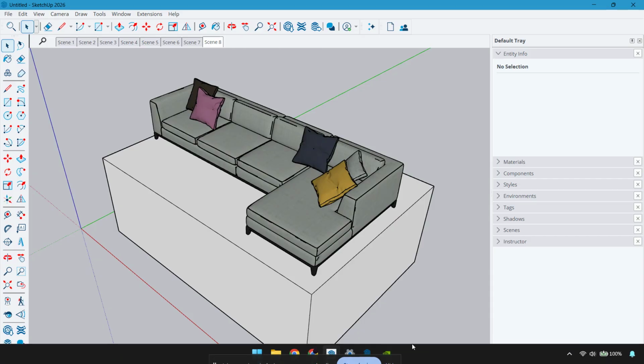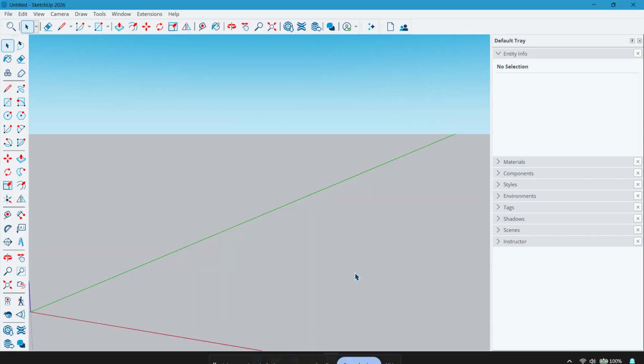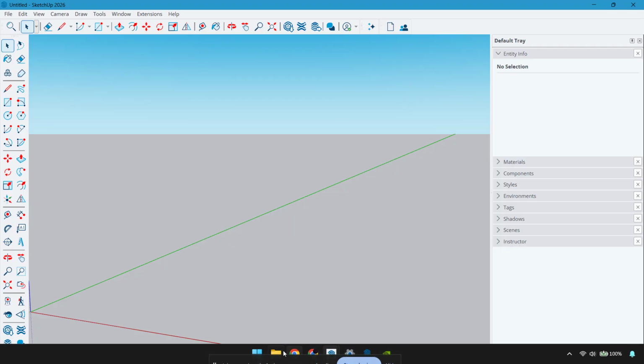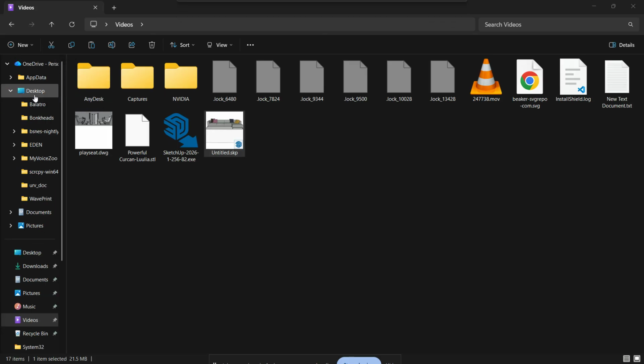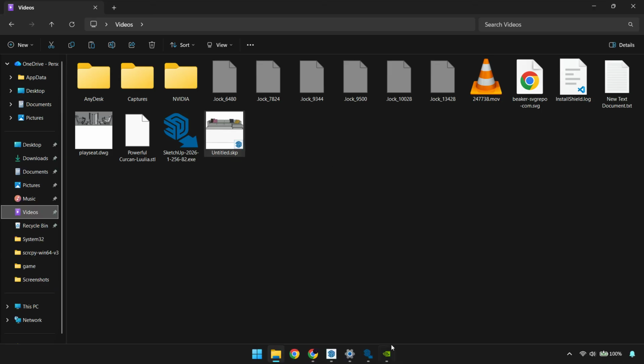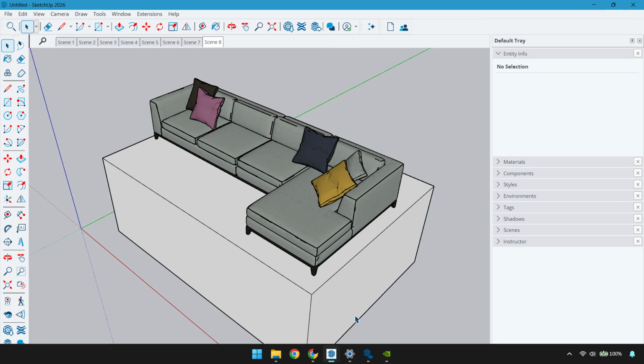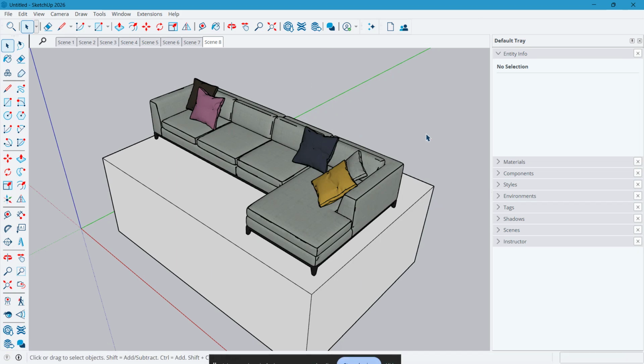So, before doing anything else, drag the file onto your desktop or into a local documents folder, then reopen it from there. If you see an error like "unexpected file format," that usually points to file corruption. This can happen if SketchUp crashed while saving or if the file was interrupted during sync or transfer. In that case, try opening the backup file we just talked about. If the backup also fails, the model may be seriously damaged.